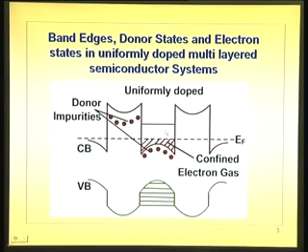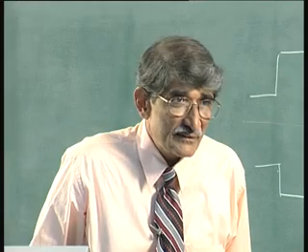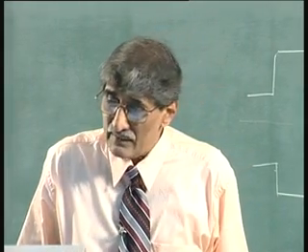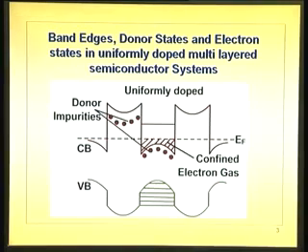You will see as we go on after some discussing the HEMT, etc., you will see these have some specific applications. In fact, you can specifically see if I have a structure like this, you can confine your electrons into this portion. We have discussed this last time. This is the delta E c which comes up, and these circles which are shown here, they are the donor impurities. Okay. And these are also donor impurities. They are both N and N. It is not N and P. What we discussed last time was N and P, but N and N, that is a different type of heterostructure. Okay. Isotype, other one is anisotype.